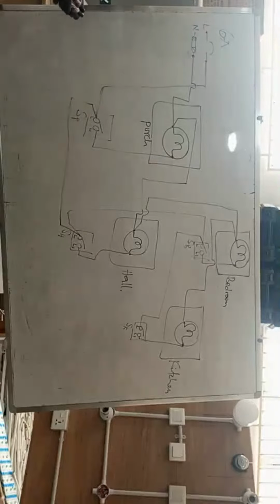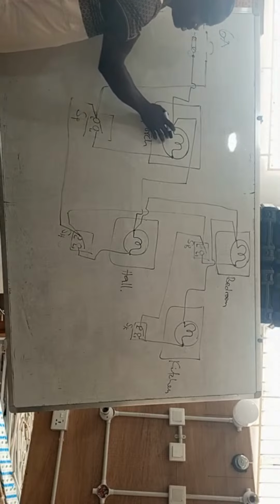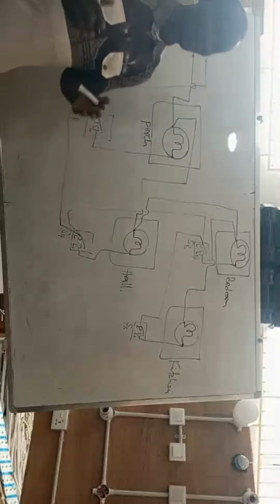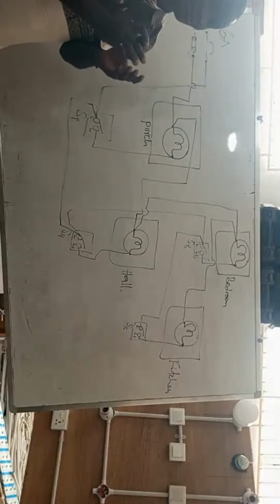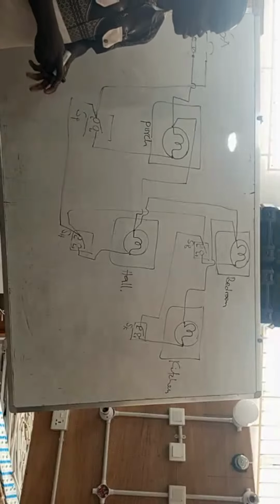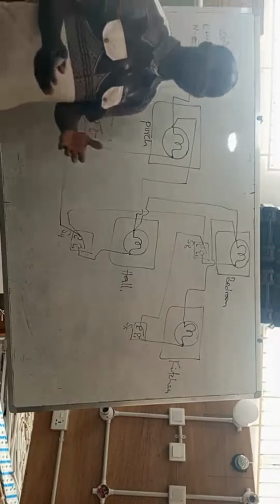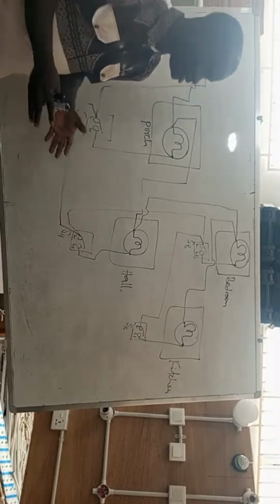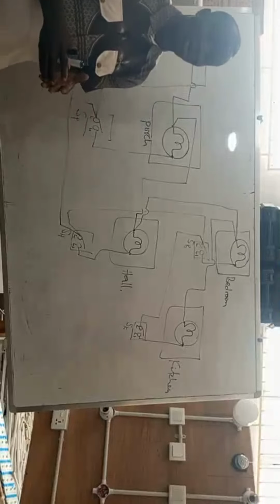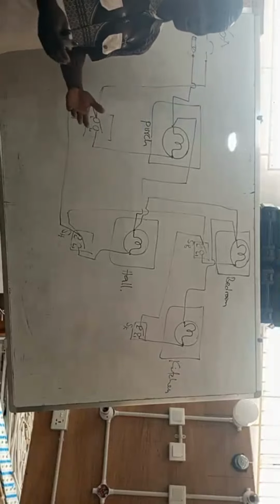And again, we also have to provide earthing connection, cables or earth wires at all the lamps. There are some lamps that come with metal bodies. The body of the lamp or the luminaire is made up of metal. Usually it could happen that the first time you are doing the wiring, you may not be using lamps that come with metals included.